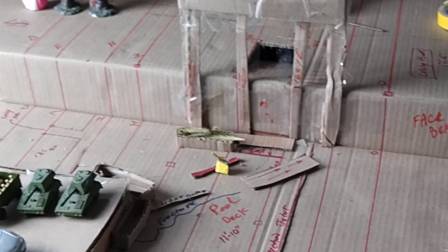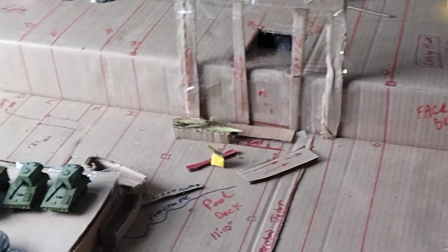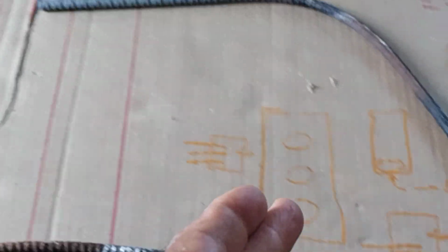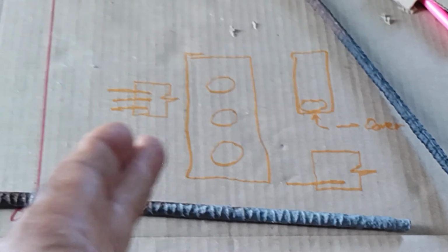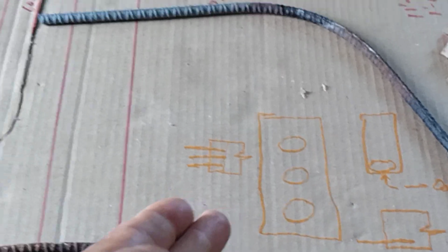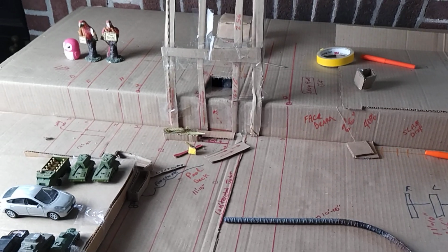Stay focused. So look at this one, but don't lose focus on where we're at. I don't want you to get left hand, right hand, smoke and mirrors, magician type stuff going on. I want you to stay focused on our path first. I want you to start seeing the multiple reasons why it failed and went that way, and I also want you to start exploring what would have stopped it, even without the BMA. Would the construction joint have stopped it? I would theorize it would. Okay, terminating video.